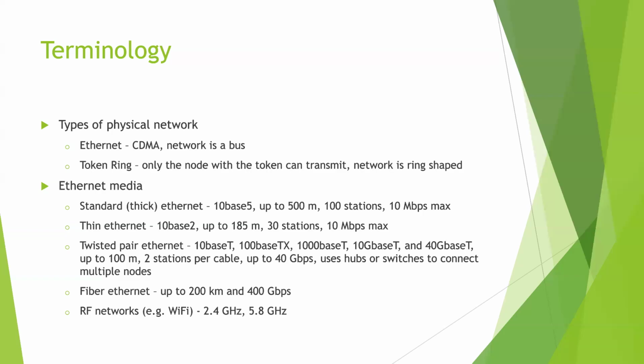There were a couple of ways to do it. You could either cut the cable, put a connector on both ends, and put your transceiver in the middle, or the most common was the vampire tap. If you ever find a stretch of cable and it's got little black dots like every meter and a half on it, that's thick Ethernet, usually yellow cable with little black dots painted on it. And each black dot was a point where you could put a transceiver. If you put them too close together, they would interfere with each other. If you put them at an odd distance, it would work, but it wouldn't work well. So you wanted them at a one wavelength distance across this cable.